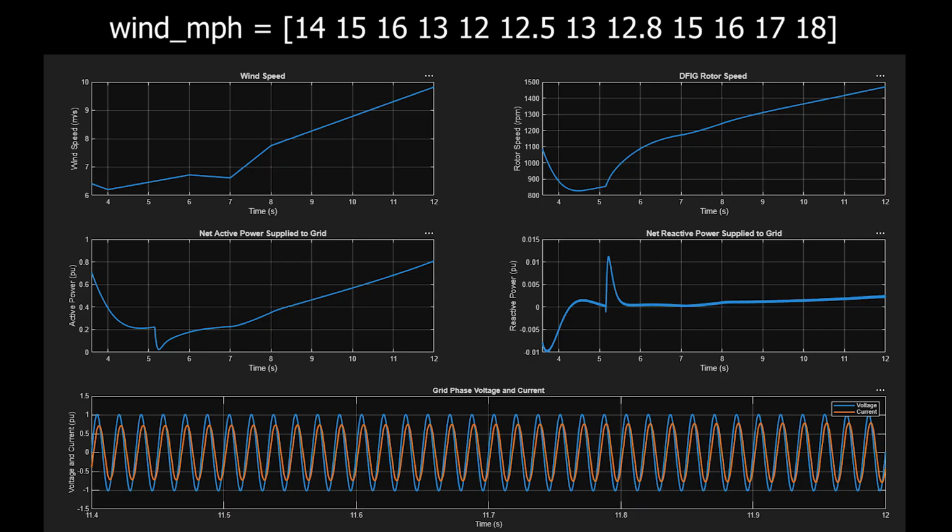However, there is a spike at point 5 due to the parameters set for the PID controller for the rotor side to match the reactive power of the grid side stator. To reduce the overshoot, lower proportional gain along with integral gain can be implemented.